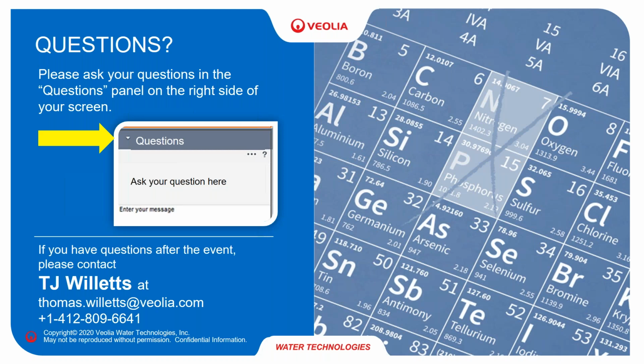So salinity is always something that we need to take into consideration. Total dissolved solids, depending on the type of solids that they are, could interfere with the biological process. So we need to know approximate ranges that we talk about. We have some applications, we have pickle juice applications for dill pickles with very high concentrations of TDS. In those cases, we also look at the full chemistry and try to figure out to what degree TDS is going to interfere with our biology.